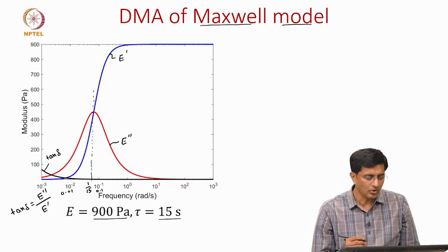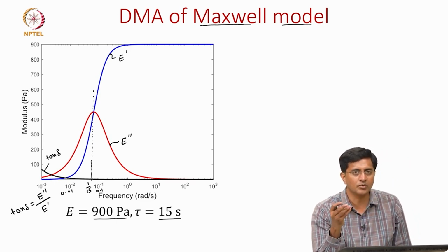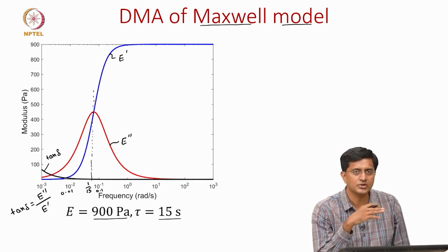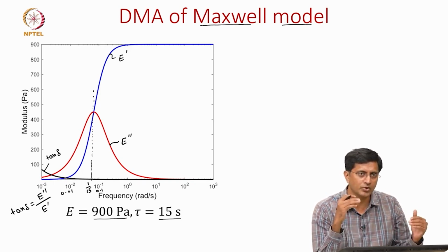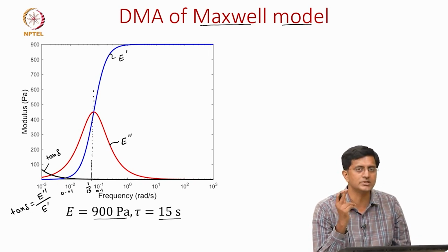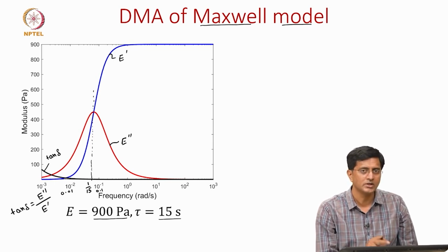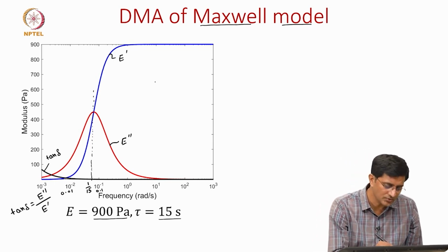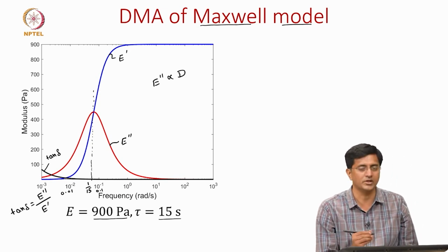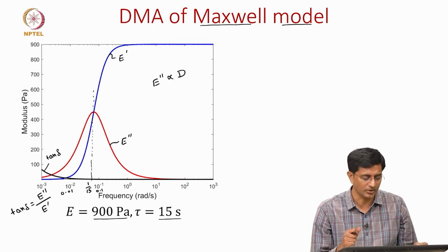Okay. So, what we are able to see is how these storage modulus and the loss modulus vary with the frequency. For the storage modulus, we said it is constant at both low and high frequencies, but at intermediate frequencies there is this significant increase. But when we come to the loss modulus, if you recall, we also said it is proportional to the dissipation in the material, so energy dissipated during this loading.